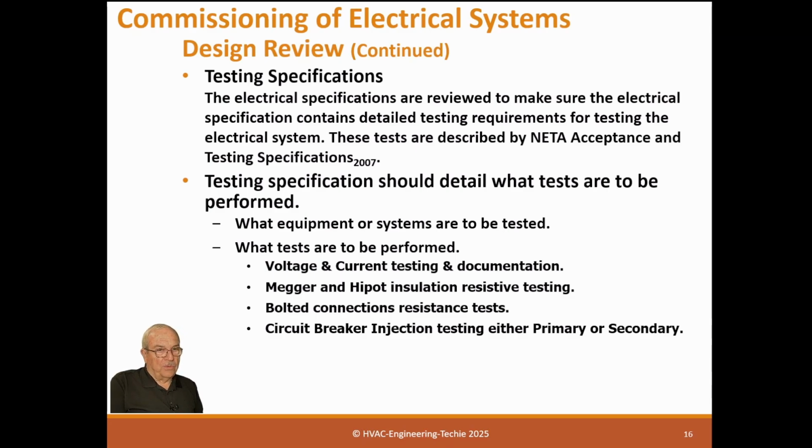So there is another way, and it's called a secondary, and secondary only tests the trip mechanism. It doesn't put full current across the switch. It just tests the actual basic circuit. The secondary injection doesn't test the whole switch. It just tests the breaker part, the part that drops the load. And these are not dangerous to it and are cheaper and easier, of course.